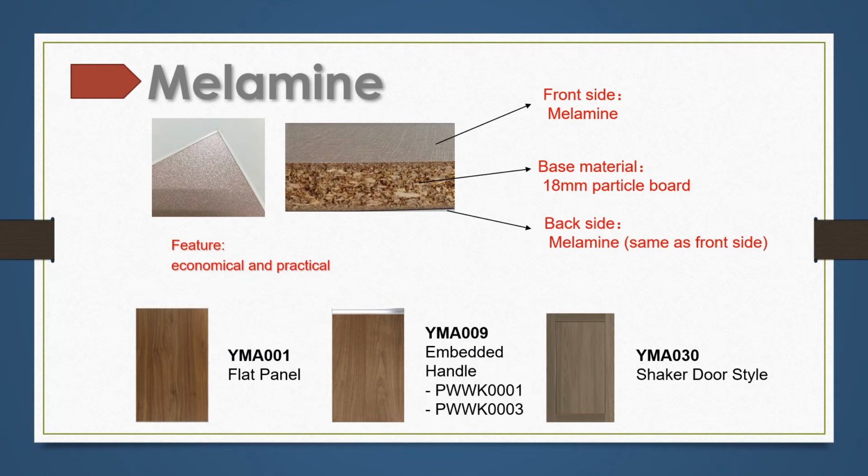Thermoplastic contains PVC and PP. These materials will soften when heated and harden when cooled. We use this feature to fix them on the door panels. The finish can cover the edges and they don't need an edge band.